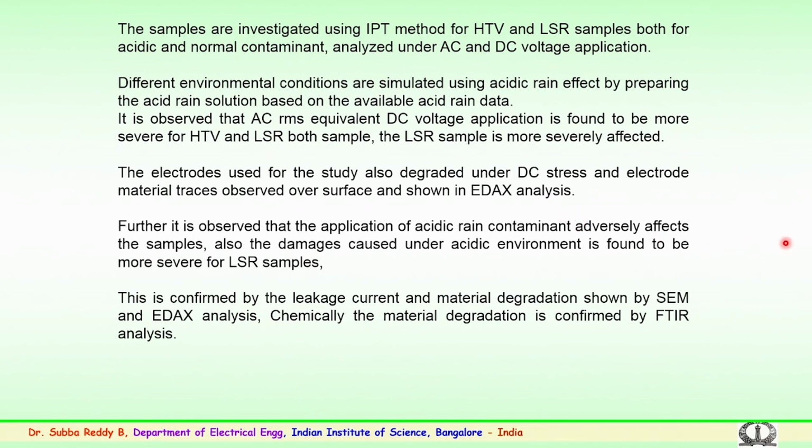The electrodes used for the experimentation were also seen to be degraded under DC stress in comparison to the AC stress, and electrode material traces were observed to be left over on the surface. This was observed in the energy dispersive X-ray analysis, EDAX analysis, which was conducted.